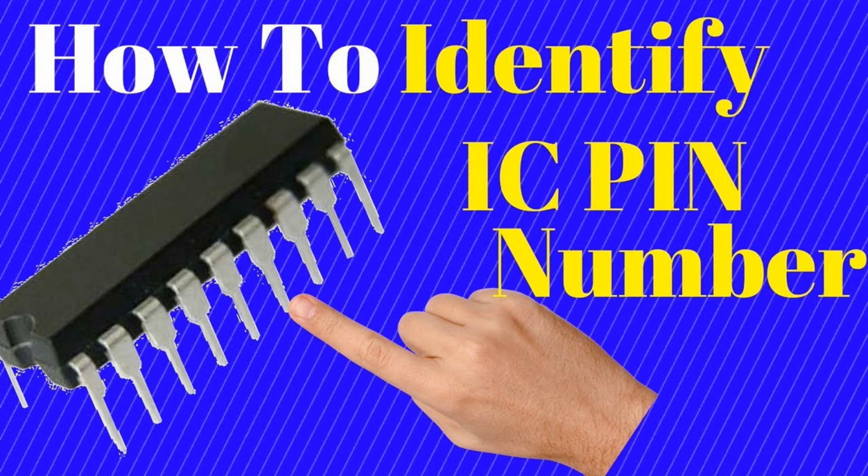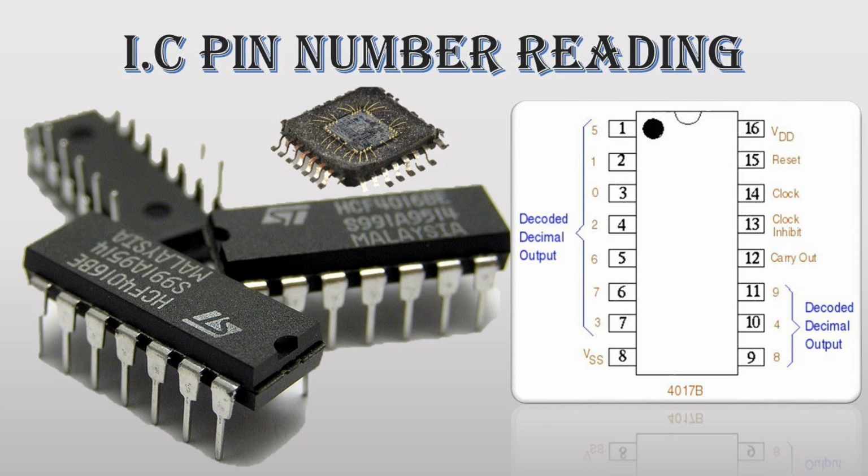Applications. MUXs are used in a wide range of applications, including data transmission, signal routing, data acquisition, and communication systems. Multiplexing ratio. The multiplexing ratio of a MUX is the number of input lines divided by the number of select lines. For example, a 4:1 MUX combines 4 input lines into 1 output with 2 select lines. Example, 4:1 MUX. Inputs A, B, C, D. Select lines S0, S1: 2 select lines to choose one of the 4 inputs. Output Y. The selected input is routed to the output based on the select lines.